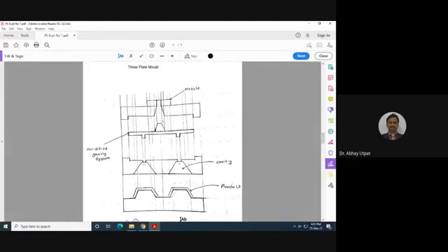Here, the first important parameter we are studying is types of molds based on number of plates. If it is 2-plated, then it is a 2-plate mold. If there are 3 plates, it is a 3-plate mold. And remember, in a 3-plate mold, the runner or gating system is between first and second, and the product is between second and third.